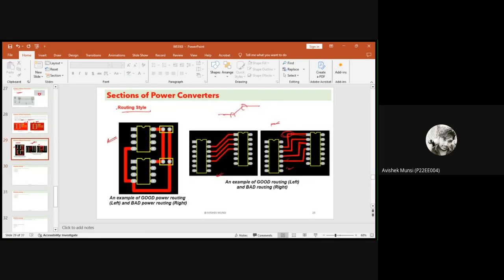So this is all for the PCB design. While designing a PCB, you have to keep in mind that first is the schematic, then you place the components, and then you route. For routing, you have to choose the trace width properly. Power requires more, signal requires a lesser trace. Then the ground plane, the power plane. If you require some planes, you have to put them properly, because if you put two planes parallel, they can introduce capacitance in between. There are a lot of pros and cons. Someone says that you need to put ground planes and power planes, you can put that. Some say that you cannot put that.